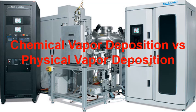That source material is evaporated, converted into a plasma or gaseous phase material, and then the same material is transported onto the surface of the substrate. So with physical vapor deposition process, basically you deposit the same type of material, which is a source material, onto a surface of the substrate. Whereas in case of chemical vapor deposition process, you basically